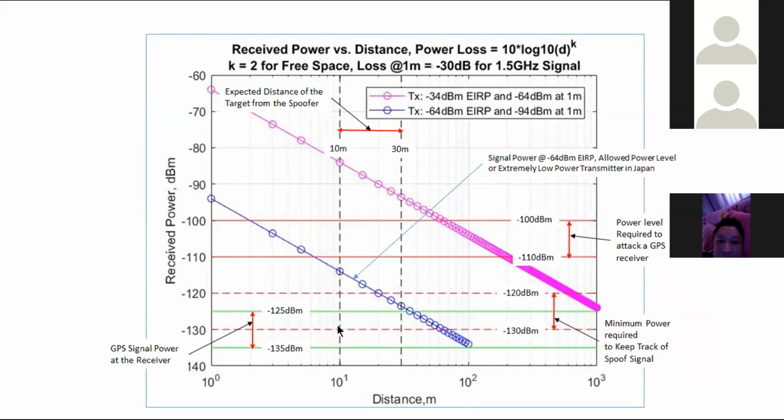And the CA code, the cross correlation properties that I showed you, has 24 dB of cross correlation. So this means if some interfering or jamming signal is coming, and if that signal is less than 24 dB stronger than the minus 130, okay. And if anything is coming above minus 110, this will totally jam your receiver, okay?